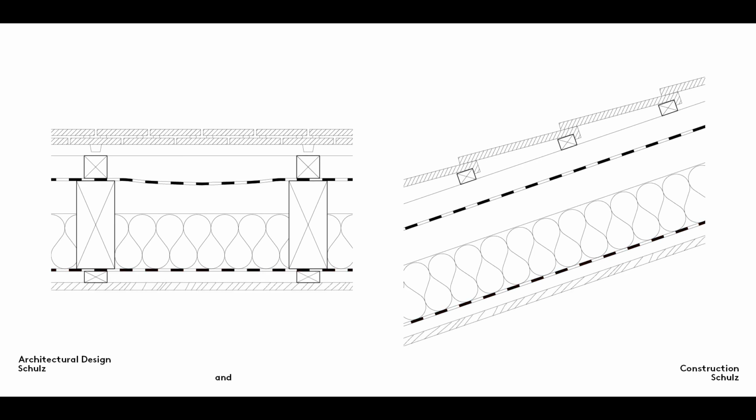The roof cladding is the final layer of the roof structure. It can consist of wooden boards or panels or plasterboard sheets that are fixed onto a substructure of wooden battens to allow for tolerances. Design and aesthetic aspects are important in this final layer. Here you can see the typical structure of a tiled roof with thermal insulation laid between the rafters. In another version, over-rafter insulation is laid on top of the rafters so that they can be left exposed in the space below. Although there is a wide range of possible structures for pitched roofs, they are all based on the superposition of a number of different layers.